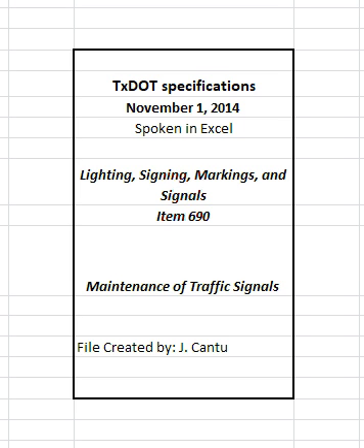4.10 Luminaire head and mast arm. Install, replace, remove, or modify luminaire heads, arms, bulbs, photocells, and hardware on timber or steel signal poles. Install material using manufacturer's specifications. Fuse luminaires individually in the signal pole handhole.